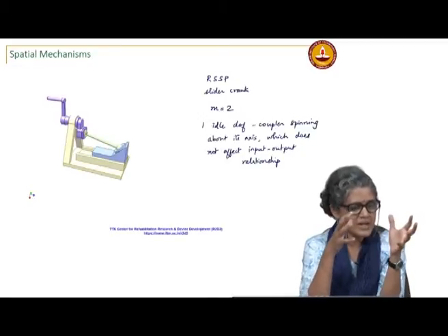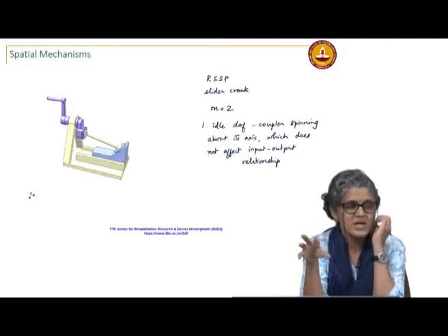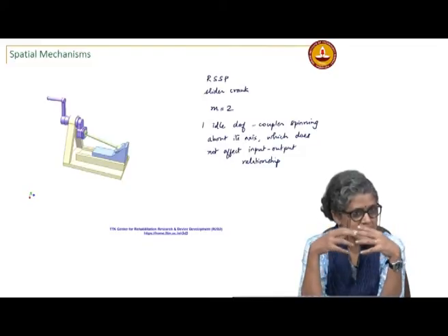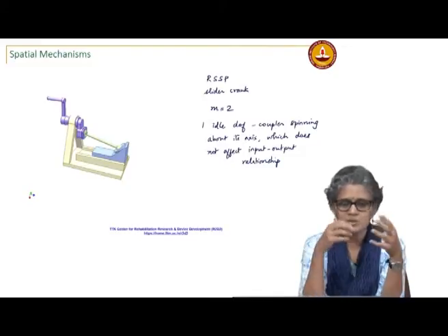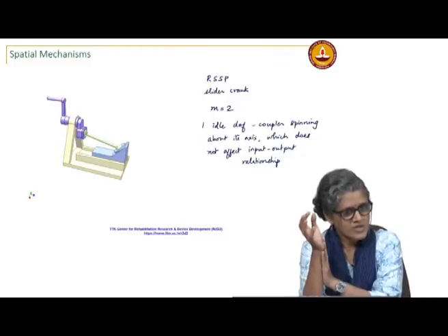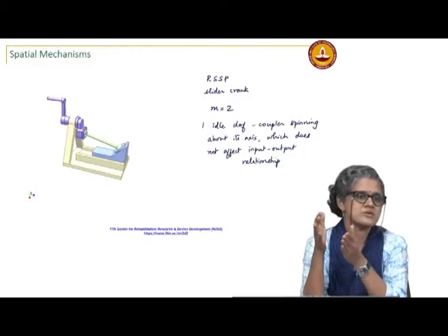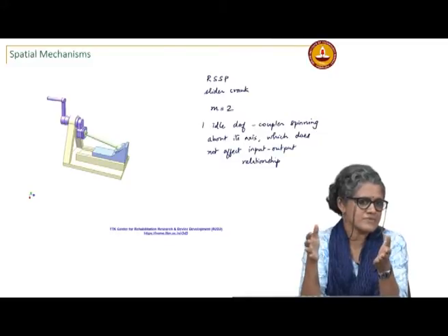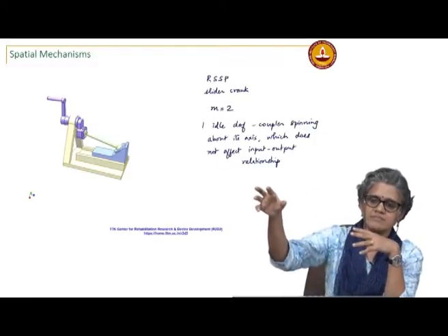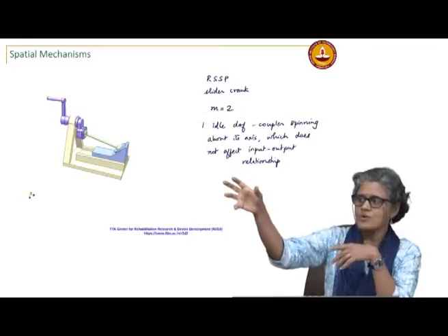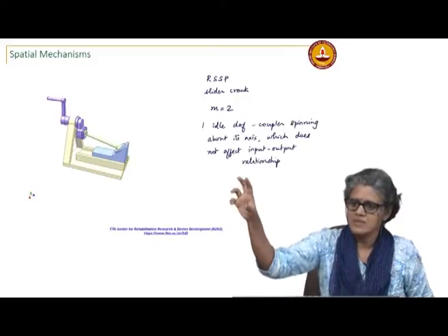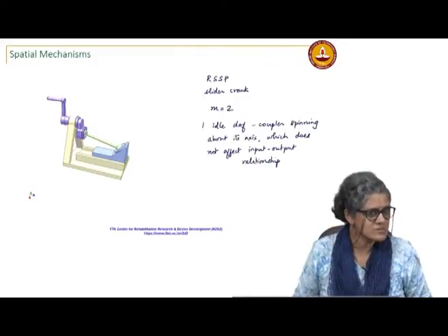That is the idea behind robotics: you attach coordinate frames and then establish the relationship between those frames, because then it becomes easier to describe the motion of all the points of interest, since the points on a specific link will be completely known with respect to the coordinate frame on that link. That is how you relate the various links. If you have a manipulator with a gripper, and you know the relationship of the gripper coordinate frame to the ground coordinate frame, then specific points on the gripper become easy to describe.